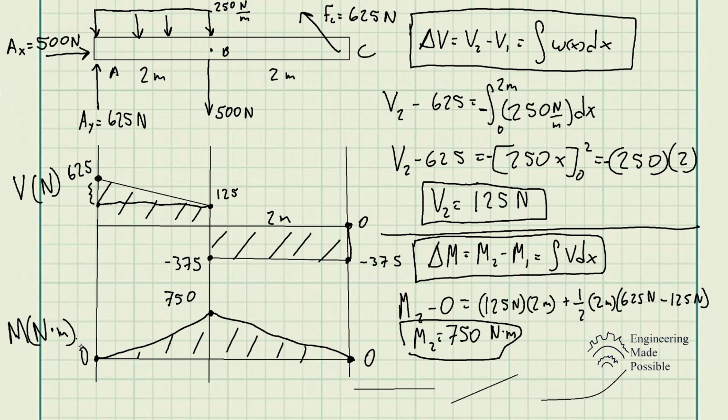And again, since the moment diagram was a lot simpler, the area under the curve as well, you just multiply, add them up, and this is how you do it. The more you practice, the easier it gets. But these relationships are the ones that you should remember, and these are the ones that you're going to be utilizing. And so this is how you do the shear and moment diagrams when it comes to having distributed loads and so forth. These two equations are going to be important to use.